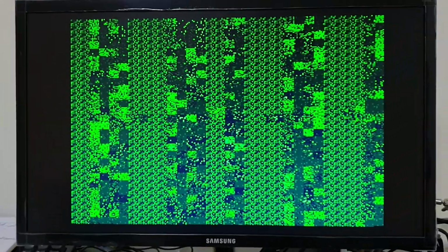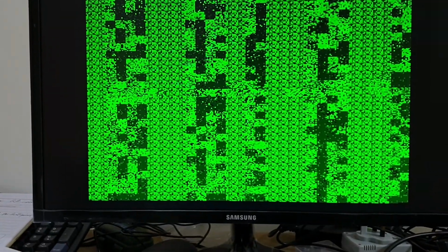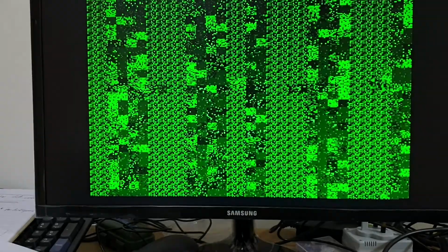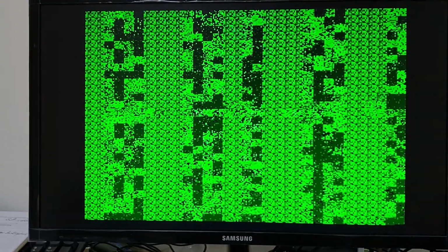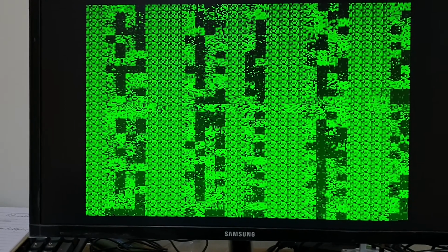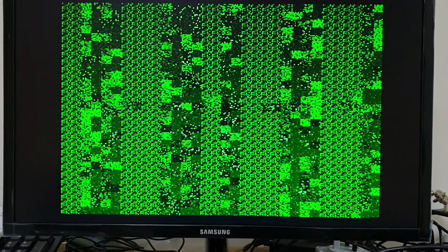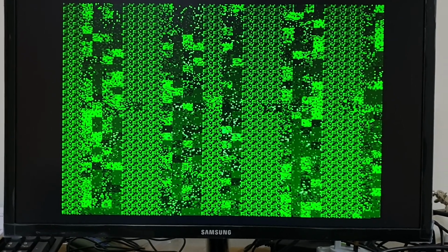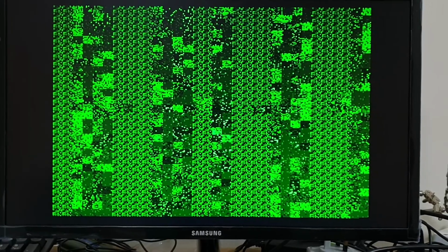So that's me tweaking the second plane pixel only, and it's flashing on and off. So there's me grounding it to logic 0, and then there's me letting it float up. So later on, if I analyze these video signals, I'll be able to see which pixels from which characters are consistently transparent, and to validate that all that's working.